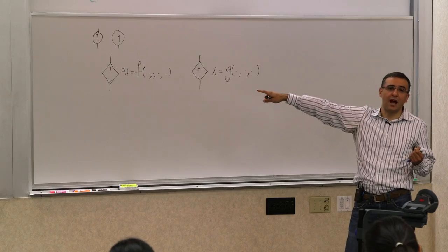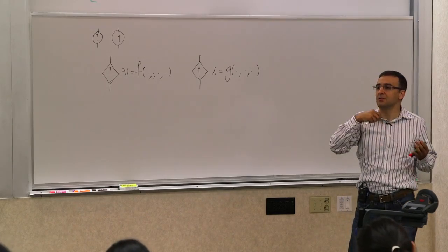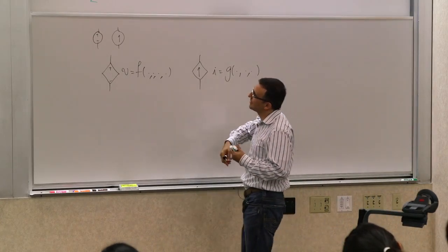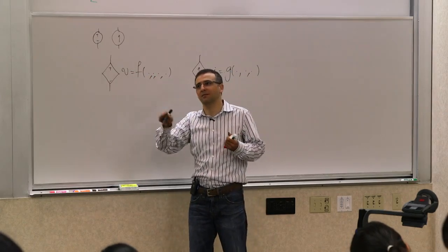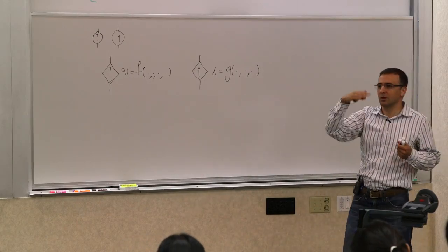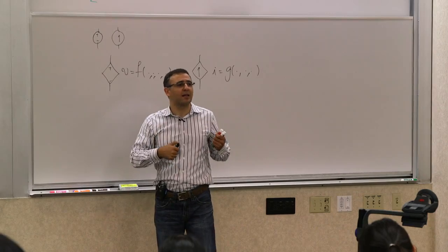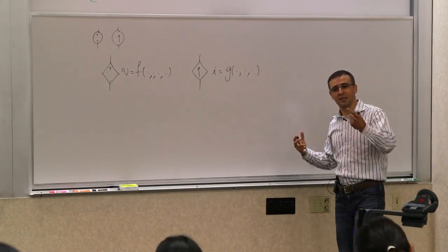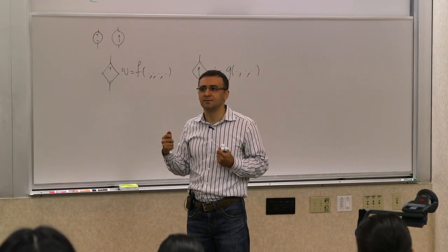So when you see one of those diamonds, it means that it's a dependent source. It means that it's not independently set. And you will see they're treated very differently, and they behave very differently. These dependent sources, there are 4 special cases: a voltage-dependent voltage source, voltage-dependent current source, current-dependent voltage source, current-dependent current source. And again, all of them are a special subset of all of the combinations you can have. But you will see they're useful in modeling things like transistors, things like that, 3-terminal devices. All of those things can be modeled with something like that. Any questions?